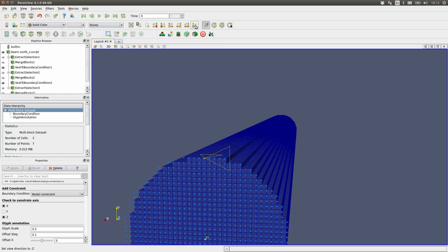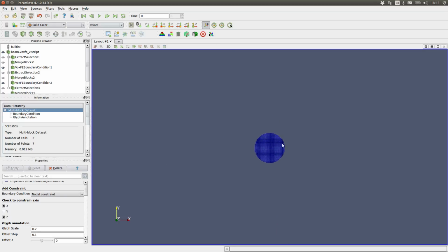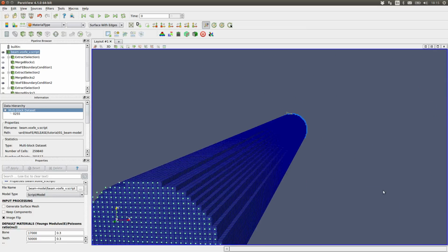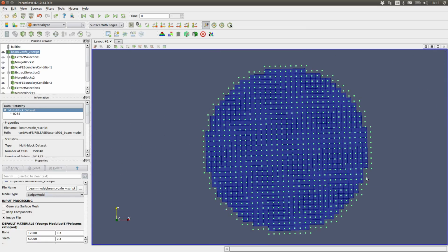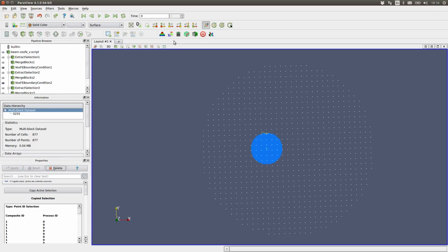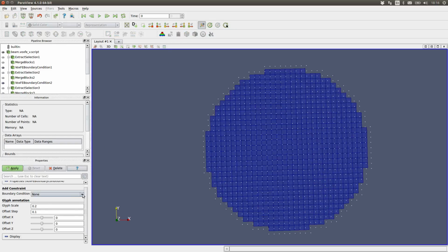If I now choose the other -Z alignment and do my right click and drag, basically this is a whole lot easier at this end. We want to choose every node, make sure that it's not overlapping or choosing any extra ones, and then we extract, apply, and add the force parallel boundary condition, which we want to be -y magnitude 10, and not on every node.